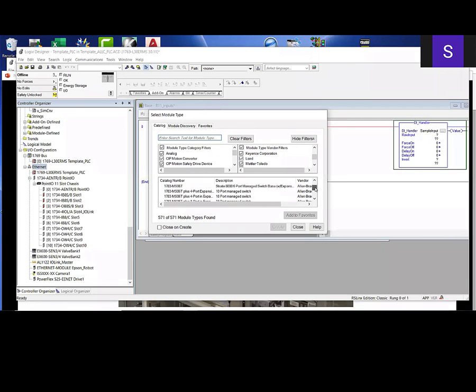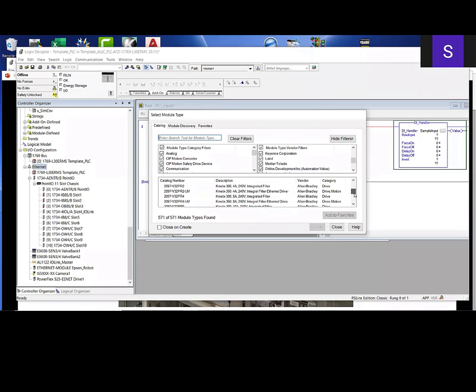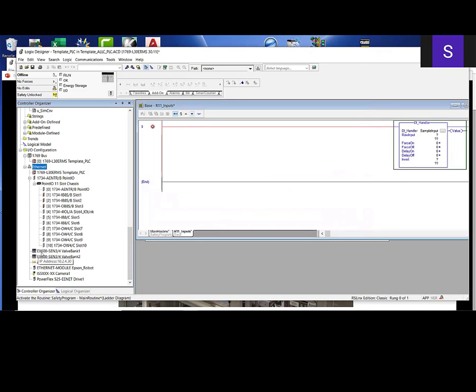So Keyence devices, and you have the ability to add any of these devices, but you have to import them first. Again, for those of you who are Siemens people, this is the same as your GSD files, which are generic system description files, right? So you can see here, you can now select this. If you did that, you would have to do more or less the same things that I did here, which is this valve bank has an IP address, 10.2.4.30. Here's 10.2.4.31.